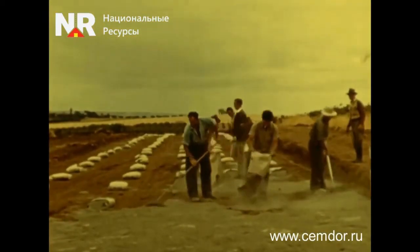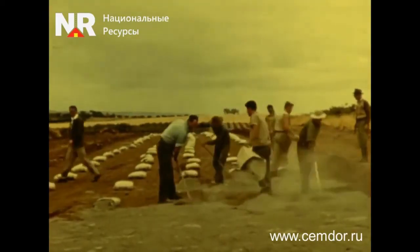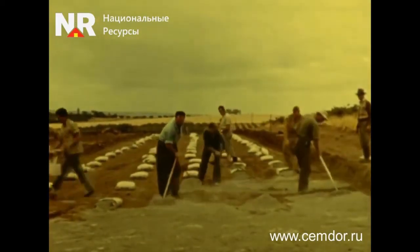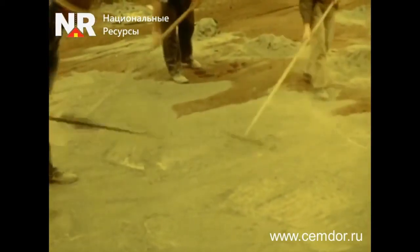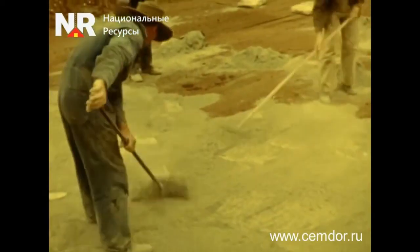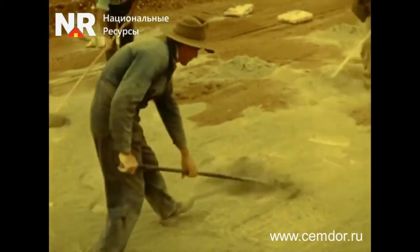Next, the cement is evenly spread over the entire area of the road section under construction for subsequent mixing with the soil. The spacing between the bags is calculated based on the required cement content and the thickness of the structural layer.